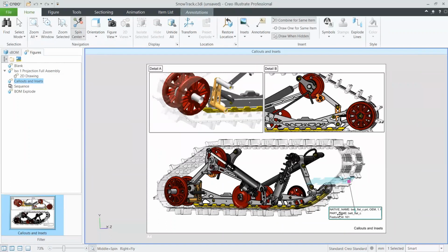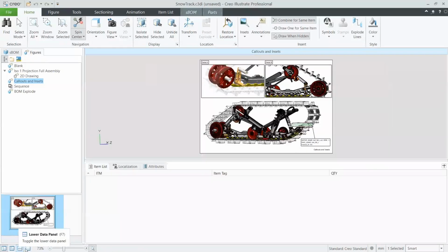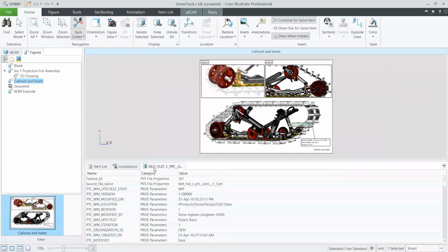And here you can also see the different parametric associations that we have here and these annotations. So these are based off of attributes that we pulled in from the CAD model. So that means that for any of these parts, again, if you were to select on something, you could see all the different associated attributes that you have. This could be metadata from the part itself. It could be attributes from Windchill, things like part name, category, different values you have there. And that's what we have in the example above.